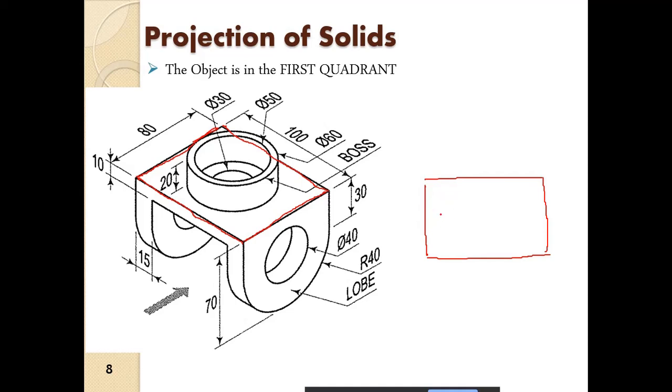All right, then here you see, this particular object has to be shown, so that will be in dotted line. Again, that other portion will be in dotted line. Right, then the annular spacing, the opening has to be shown, so that will be in dotted line. That means we cannot see them, but it is there. We have to notify the person observing the drawing that there is an opening there.